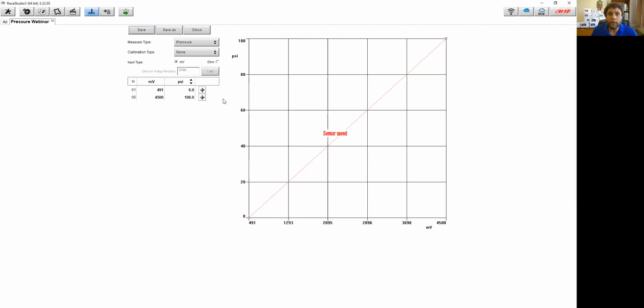Right. And even pressurize it up and have a mechanical gauge if you want to the first time, and find out that it's running at 7 PSI, and then come and find out what those millivolts are. Come in here and build your nice cool little sensor, and then from then on you have calibrated your own sensor very, very accurately. So Matt's right on the money.